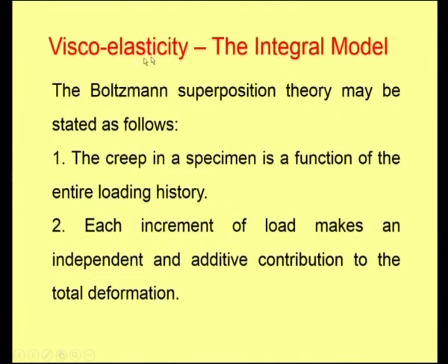First, in the integral model, we will see what is meant by the Boltzmann superposition theory. It has two components. The first one is that the creep in a specimen is a function of the entire loading history. The second one is that each increment of load makes an independent and additive contribution to the total deformation.